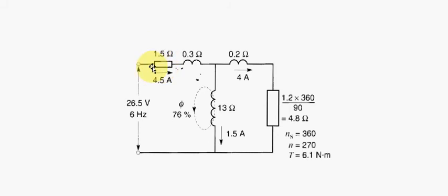But this is the stator resistance, and that doesn't change. Okay? It remains more or less constant. I mean, if you really have to be pernickety, this value here will change with temperature variations in the stator, as well as a thing called the skin effect. So as the frequency increases, the skin effect comes more into play. So this value will increase, but marginally.